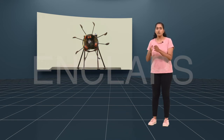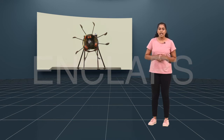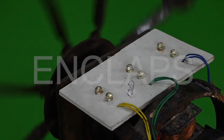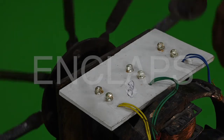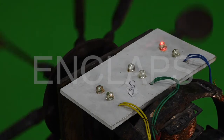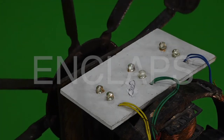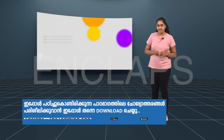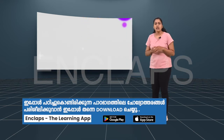When the field magnet rotates, an EMF is induced in those 3 armature coils and as a result, AC current is induced in them. 3 alternating currents of different phases are generated simultaneously in the 3 armatures. In each armature, maximum and minimum EMFs are generated at different instances. Therefore, it is called a 3-phase generator. Now, you understand how mechanical energy is transformed into electrical energy inside the generator.